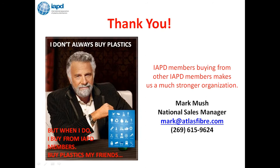When it comes to sheet rod, you won't see any of that. You will get no voids, no porosity, because that rod is taken from sheet stock that has been pressed, squeezed down under immense pressure. You're starting with that homogeneous massive material, and when it's cut into square bar and then centerless ground into round bar, you're maintaining that homogeneity. So that's probably the main advantage of the sheet rod over the molded rod. You're not going to see any of those internal cracks.